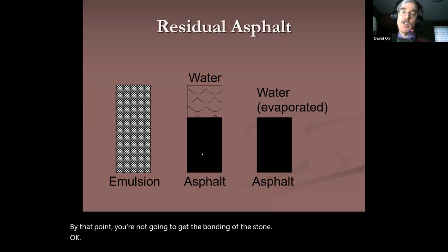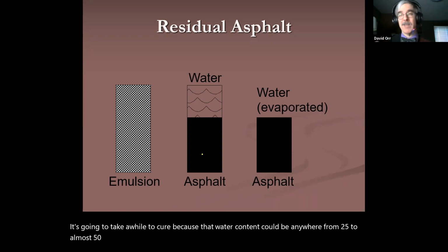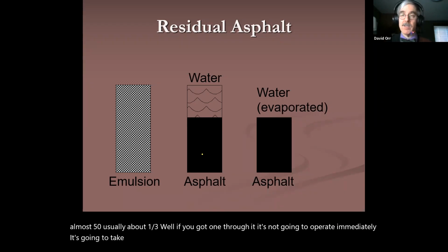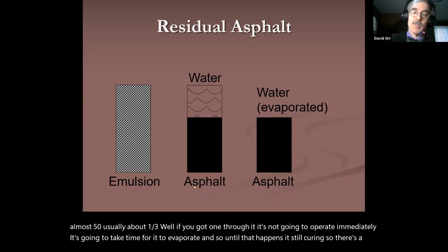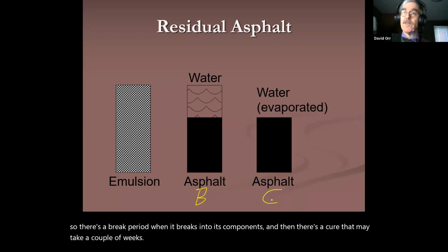It's going to take a while to cure because that water content could be anywhere from 25 to almost 50%, usually about 1/3. Well, if you got 1/3 water, it's not going to evaporate immediately. It's going to take time for it to evaporate. And so until that happens, it's still curing. So there's a break period when it breaks into its components, and then there's a cure that may take a couple of weeks. Okay? So when do we do these?